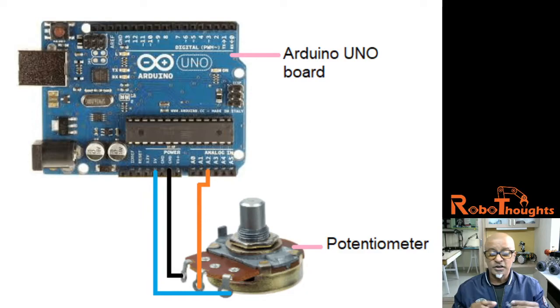So the fixed input voltage is applied across the two ends of the terminal of a potentiometer, which further produces the adjustable output voltage at the wiper or the slider. You can call it a slider. And as the slider moves from one end to another, from left to right and right to left, the divider can vary the output voltage from maximum to the ground.